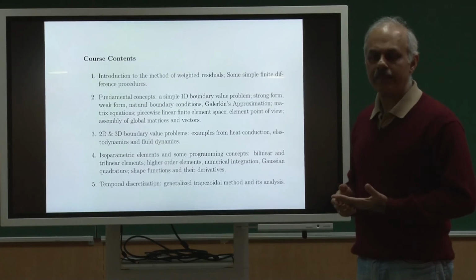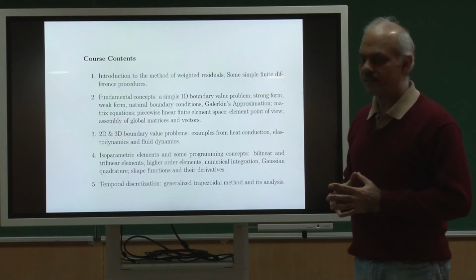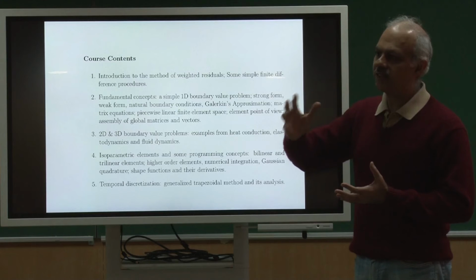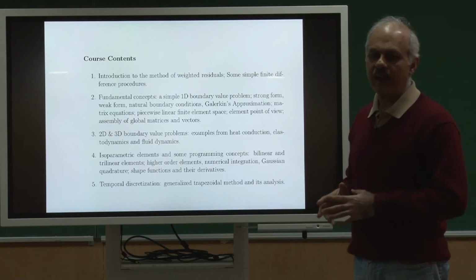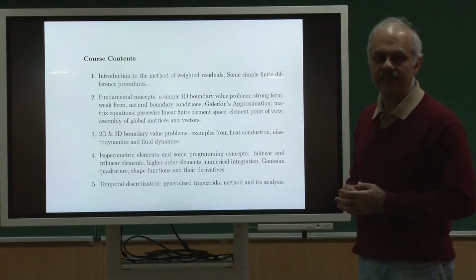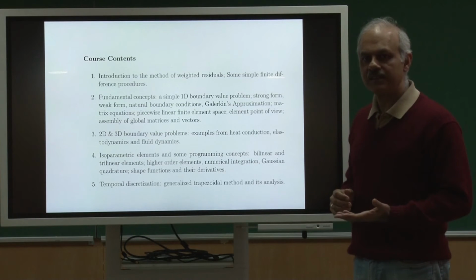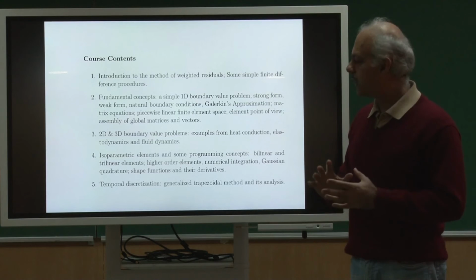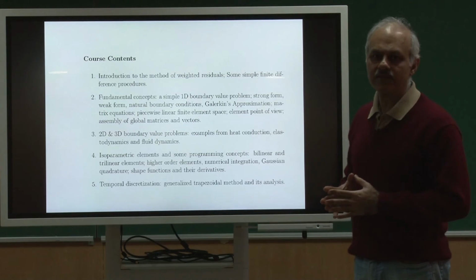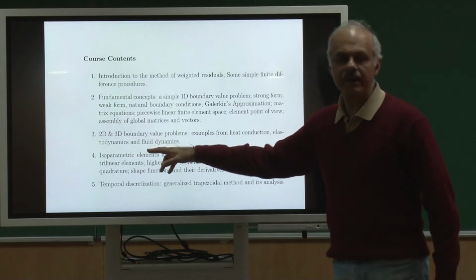Think of the following. Suppose I am interested in looking at flow past a sphere, and to represent the sphere I could say, well, the surface will be represented by higher dimensional panels, not just linear panels, not just straight panels. Okay. But the flow I would like to represent with linear elements. So, I could have higher order elements for the surface and a little bit lower order for representing my solution. So, that is not isoparametric.